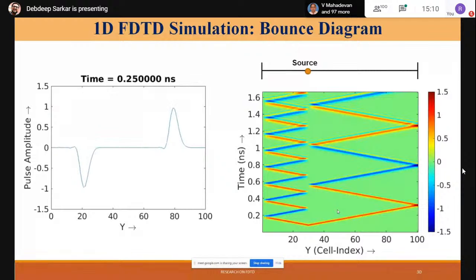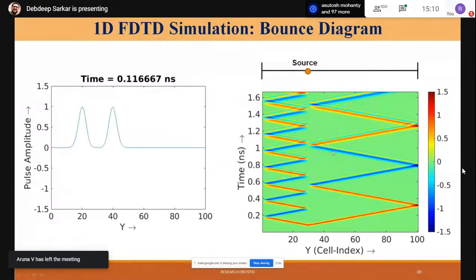You can do the simple ZL minus Z0 kind of calculation, and you will get the result why it is -1 at the short circuited boundary, and at the open circuited boundary it is basically +1. So now the beauty of the thing is, it seems that we have unknowingly created a short circuited boundary condition here, as well as a short circuited boundary condition here also. But in this case, we have an open circuited boundary condition.